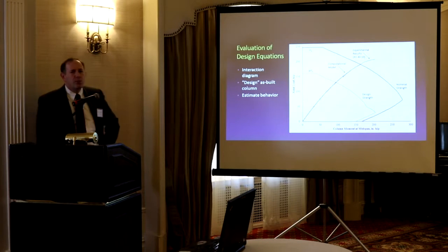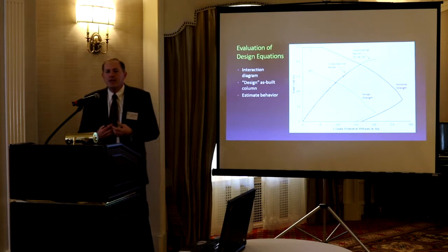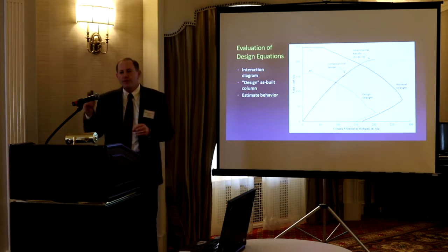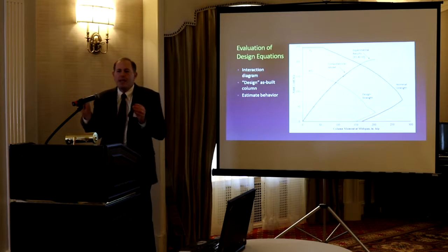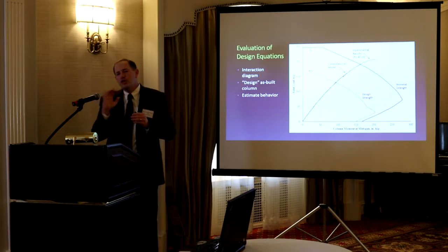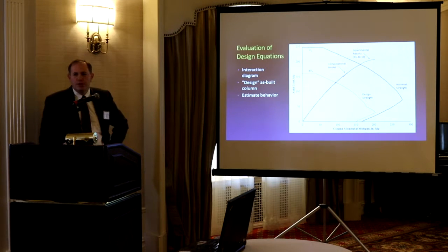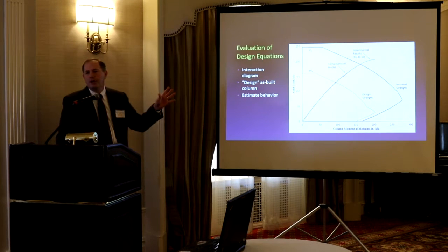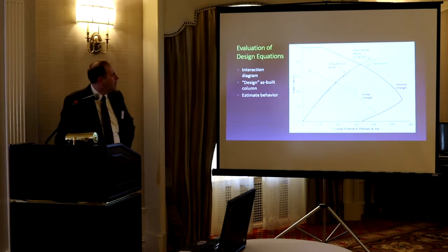There's our computational model. So when I say the model again, there is no calibration of this model. This thing is just plugging in E of 57 root f'c. It's plugging in the Hognestad stress-strain curve. We didn't tweak anything to make it fit. It is just using regular mechanics, and we can predict the second order effects, short-term loads perfectly. I mean, it was uncanny how well these things can predict.